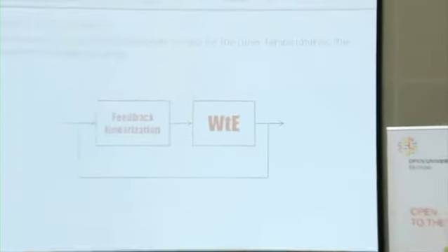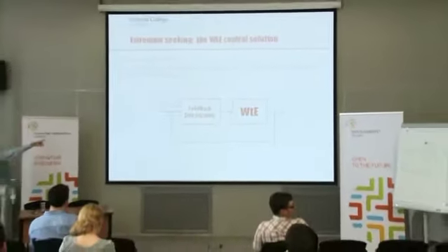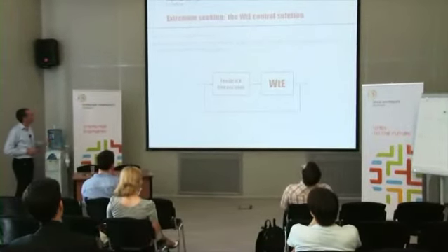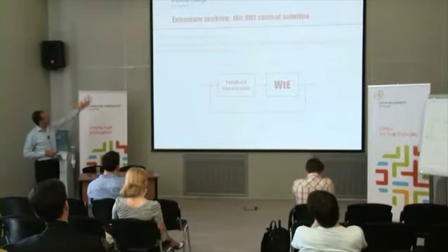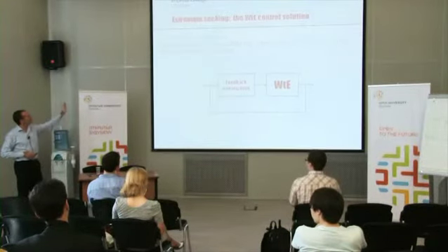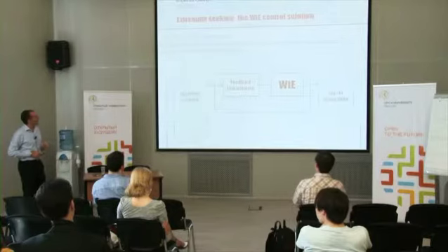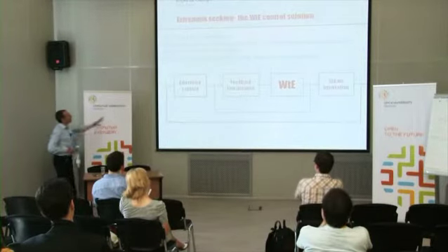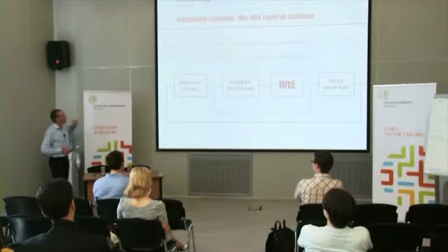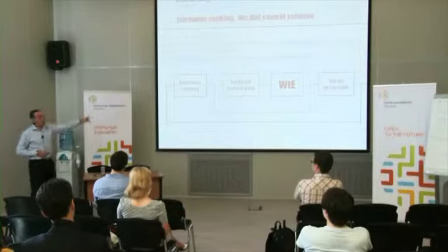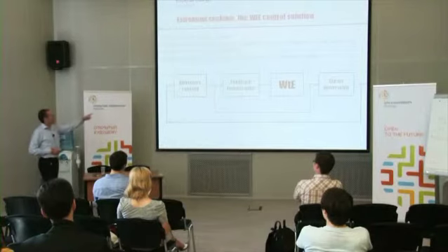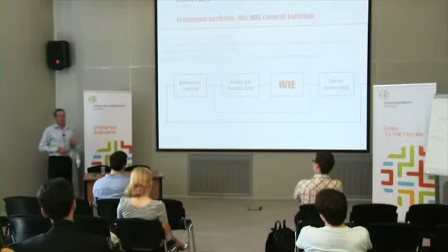So we now implement a control algorithm which has two loops. In the first loop, we set temperatures of the piles, so temperature inside the chamber that is wasting, and the oxygen and the waste throughput. So we apply this so-called feedback linearizing controller in order to make sure that all these parameters are set. And then we have a second loop, which is composed by the steam generation. So you measure steam, and then you close the extremum seeking loop. This means that you achieve all your goals: oxygen, waste throughput, temperature inside the chambers. On top of this, you maximize the steam that you produce.